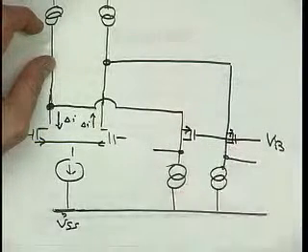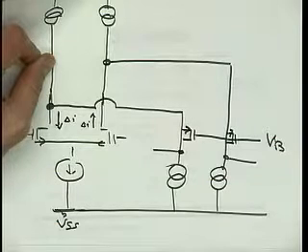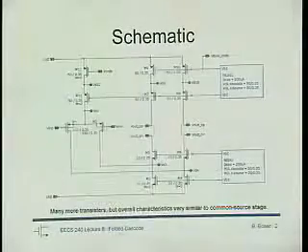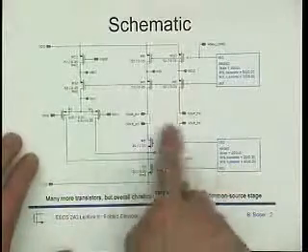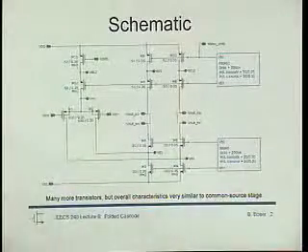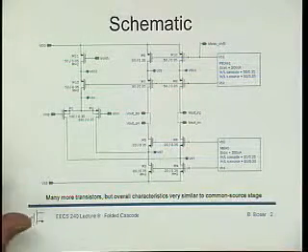We have a relatively modest FT, and what's the problem with that? Yeah. It can be that the second pole comes near the... And then we get a relatively modest phase margin, right? So this solution probably ends up with better phase margin because we have the fast device here. So maybe we build an overall slightly slower amplifier, but then we get good phase margin.